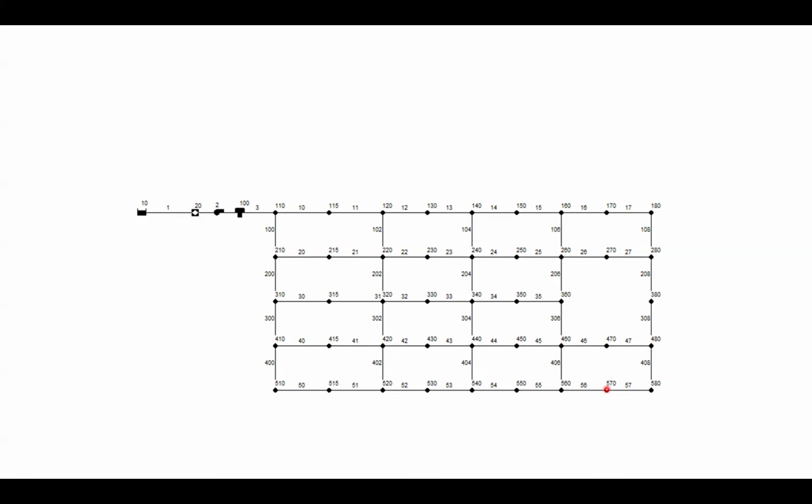These nodes are where we're going to have demand. And so you're going to actually put a value in there, cubic feet per second, of water leaving the network. That water is going into the warehouse. It's going to go out into the sewer. It's leaving the pressurized water supply network. So water is coming in here at the tower, and then each of these nodes is going to have a different demand based on the makeup of the block.